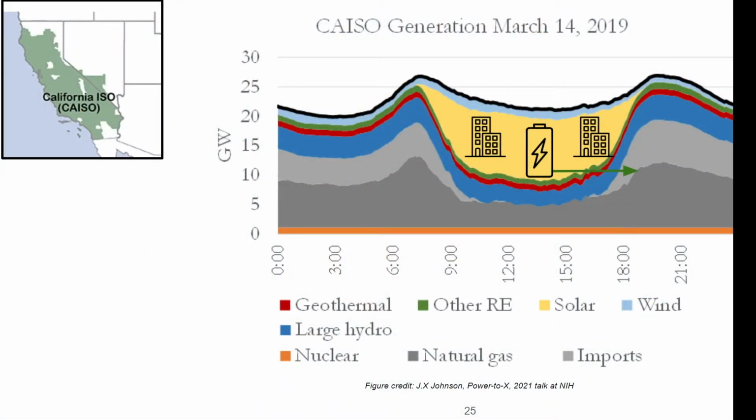The second form of solution is really looking at our demand. Like I said, traditionally we like to control our generation to match the demand, but a new form of service is demand-side services, where you actually control demand to match your supply. One example is the air conditioning and thermostat programs that utilities have.